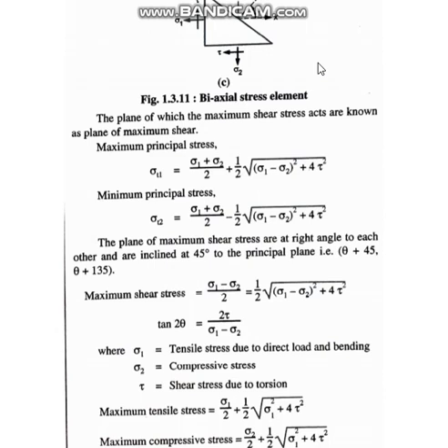On a machine component there are not only direct stresses, but sometimes bending moments, shear stresses and torsional shear stresses, so many other stresses may be coming. When all these stresses are resolved, we find that there are certain planes on which only direct stresses are present. That means no shear stresses, only direct stresses.